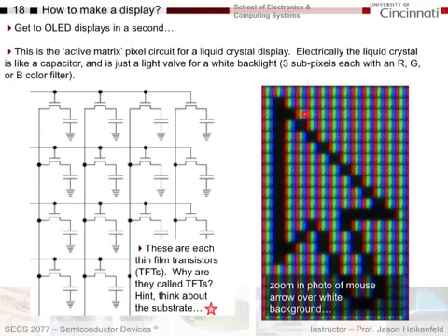Okay? So the question is, how in the world do you electrically drive a huge array like this? Imagine if I have a typical LCD display which has 1,000 by 2,000 pixels. Let's say I have 2,000 this way and I have 1,000 this way, that would be 2 million pixels, right? If you multiply all the rows and the columns together. Well, I cannot bring 2 million electrodes into a display and control them all. Your LCD TV or your smartphone would have a huge wire bundle on the back of 2 million wire connections going to every single pixel.